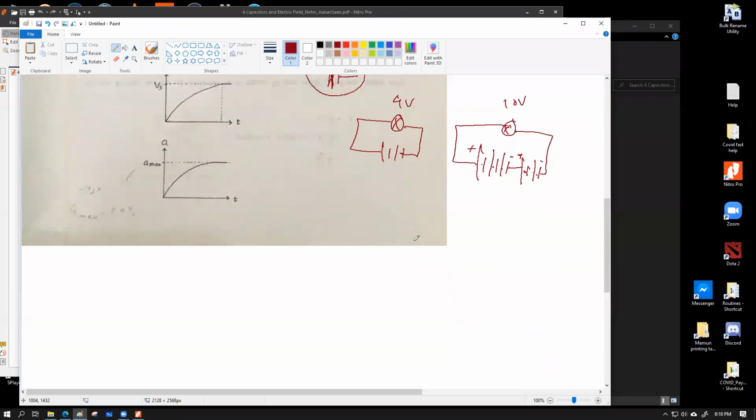So what is actually happening? Why should that be 2 volts? Let me just draw this up. So this is this, and let's say I'm going to add 3 over here, and then the reverse 2 over here. Good. So if you connect a battery system like this, the total amount of voltage available to this bulb is going to be only 2 volt, where this is going to be the positive side and this is going to be the negative side.